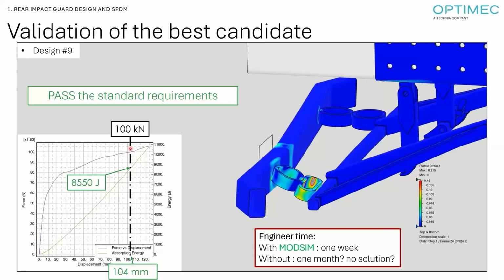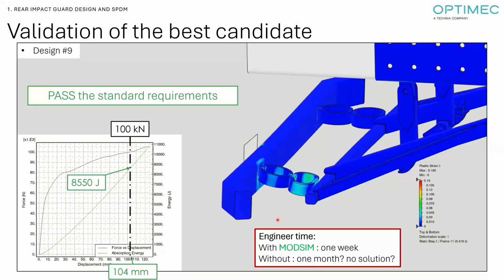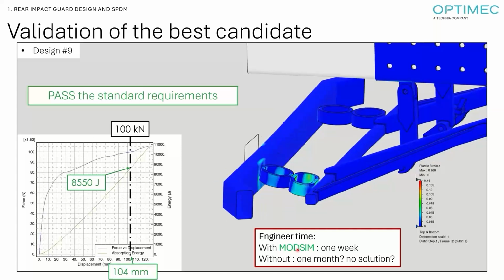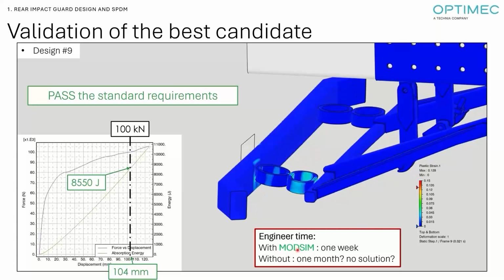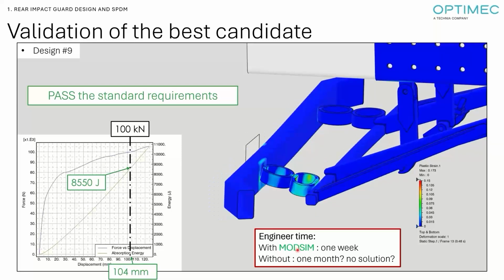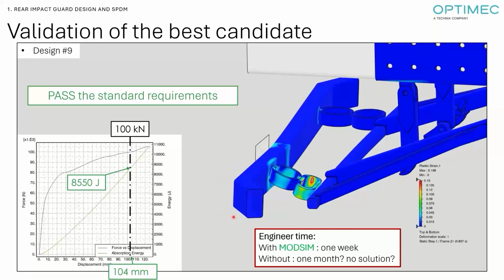So using that approach, that Dassault Systèmes calls ModSim, which is a contraction of modeling and simulation, because you have everything included inside the same platform, you have the parametric optimization, the parametric design from CATIA, allowing you to update and generate the design automatically. And you have your FEM and your scenario linked to the CAD because you are using the same graphical interface with no file transfer. You are unlocking this type of workflow in which you let the algorithm find the design for you.